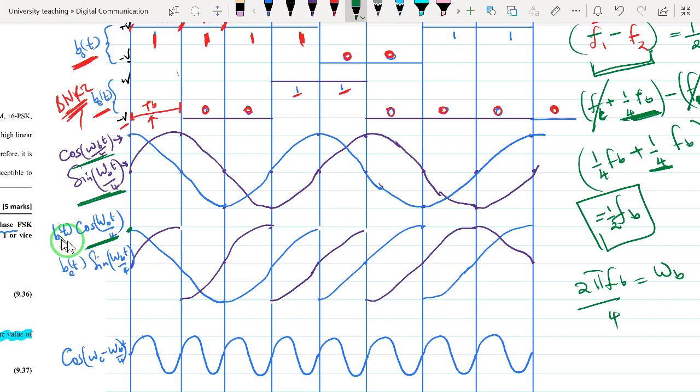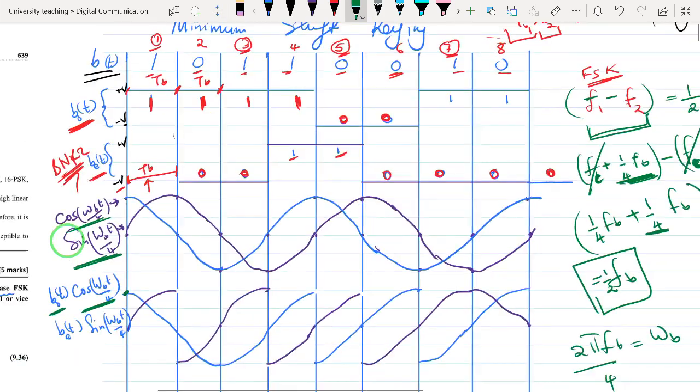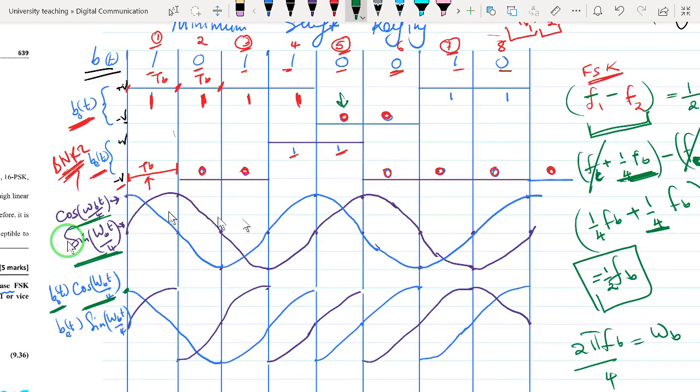What we'll do is multiply the cosine wave that we have generated with our odd bit stream. And what we know is that when we multiply a cosine with a -1, remember that -1 is the one represented by this. With bipolar NRZ, positive voltage is equivalent to 1 for our purposes, and negative voltage is equivalent to -1. So when you multiply a cosine with a -1, it is going to change phase, and I think we will see this at this point. Remember, this blue one is represented by this blue one.